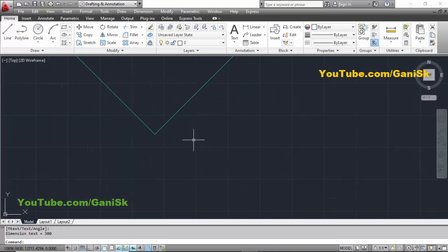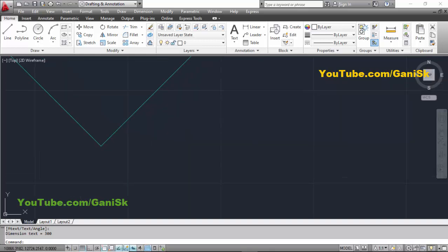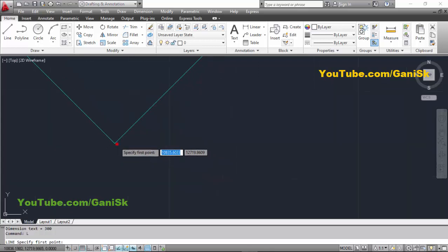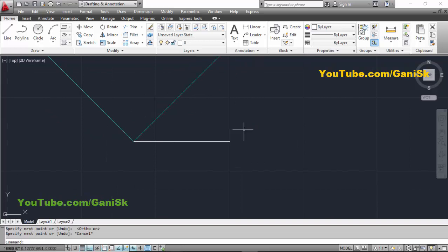Now we're going to check the angle. Before checking the angle, we need to place a small line here. For the line command, type L, enter, and pick the first point here. To get the horizontal distance you need to activate the ortho shortcut F8 on your keyboard. Now click on here to place the line, and click on Escape to exit the command.